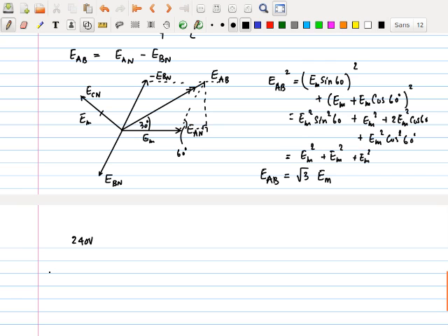So if you take the voltage between lines, that will be what? Root 3 into 240. Usually for a 3-phase circuit, in your advanced level, you would learn that line to line voltage is around how much? 400 volts. 415, 400 volts.